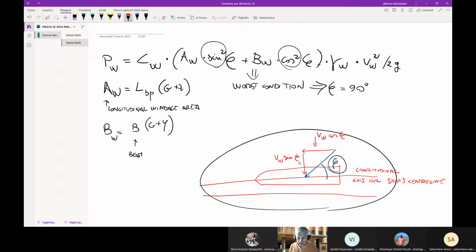There is a second multiplication which is applied in order to introduce a correction factor for the friction, because actually the wind speed is transformed into a forcing through friction, and therefore the second multiplication also takes into account friction, because in this way we take into account that the real forcing is given by the wind speed multiplied by a friction. I hope I was clear.